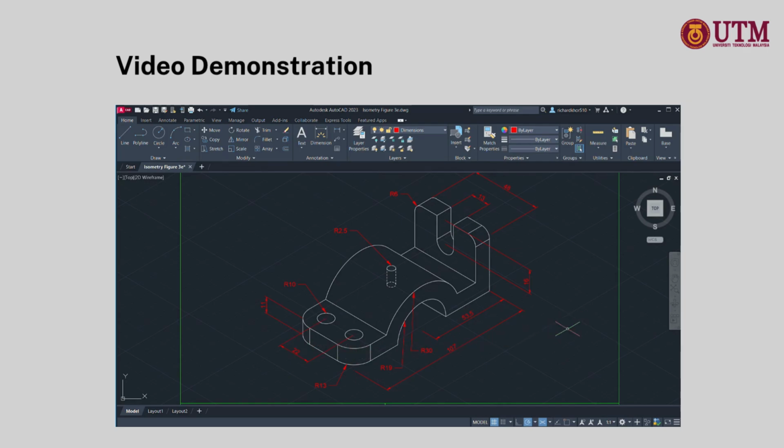Material specification. In a typical mechanical equipment drawing, which section is made of which material should be stated. For example, whether it is stainless steel or carbon steel, as this affects the corrosion resistance, cost, and the design of the equipment. Weld locations are something that would be common inside drawings as well, as they should be identified clearly, since they will affect the fabrication quality. For example, pressurized vessels and pressurized tanks will require a higher quality of welds.